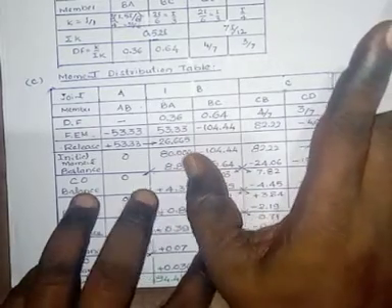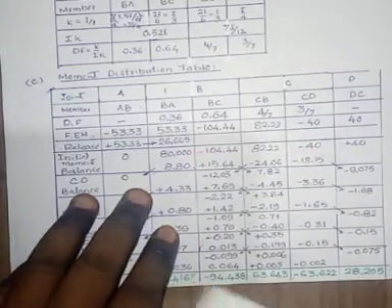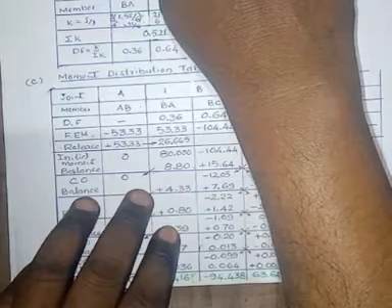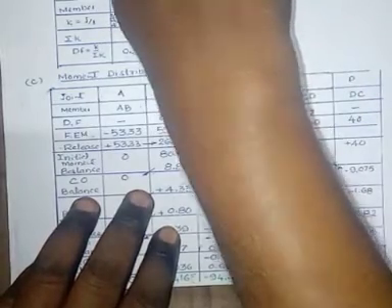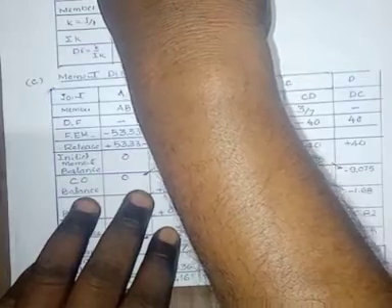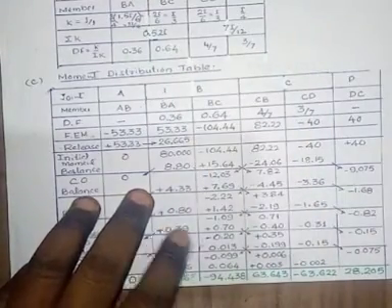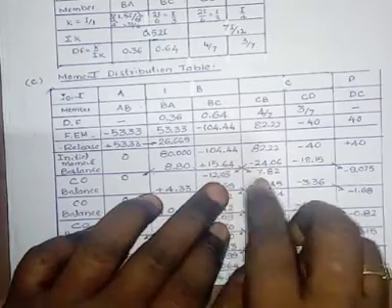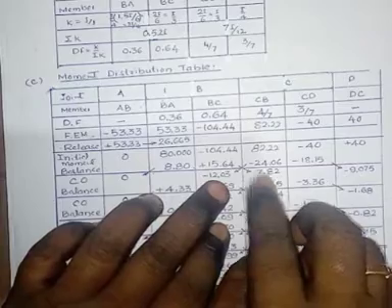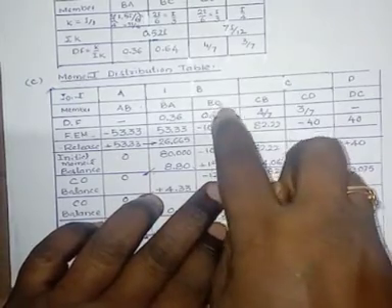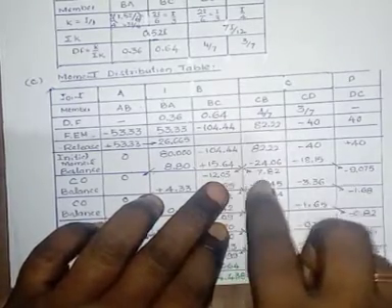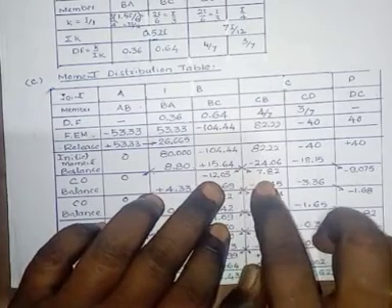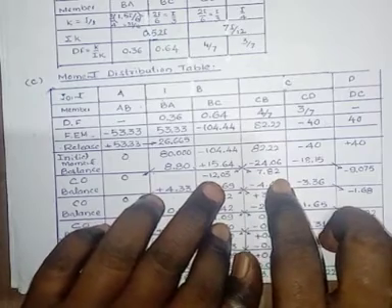Here, by observing this, B to A, there is no carryover since this one is end support which is on simple support. Then from B to C, there is 50% of the moment carried from B to C. Here I have shown the arrow mark, that is half of that with same sign. Here this is 15.64, half of that, that is 7.82 with positive sign.